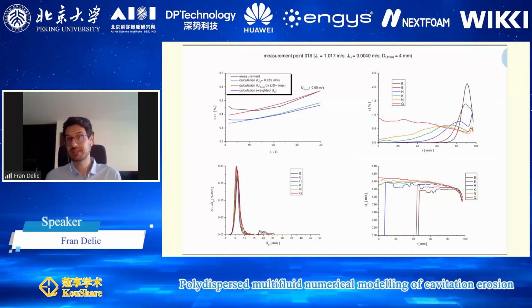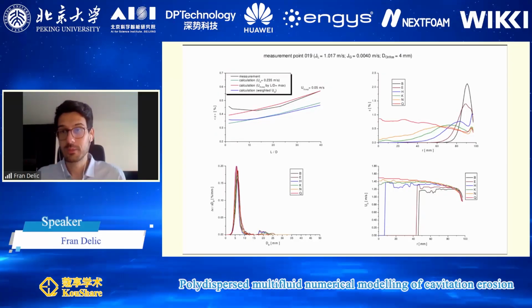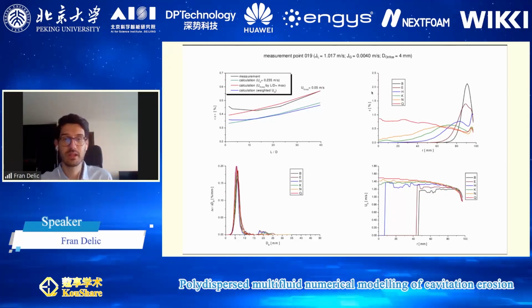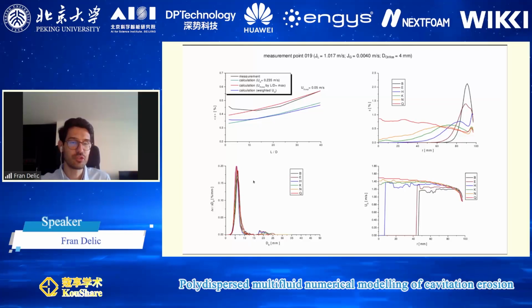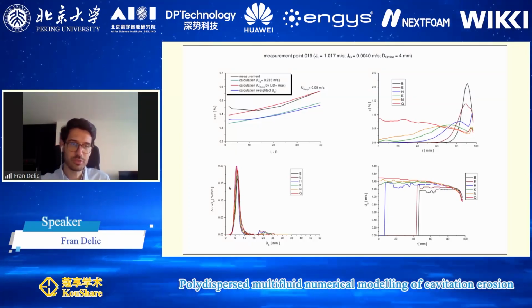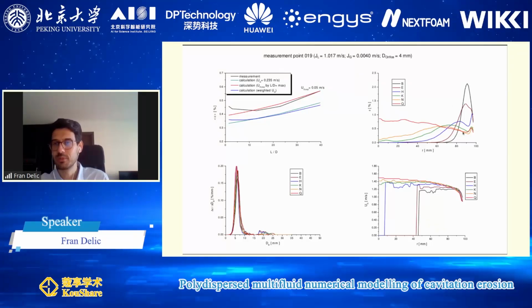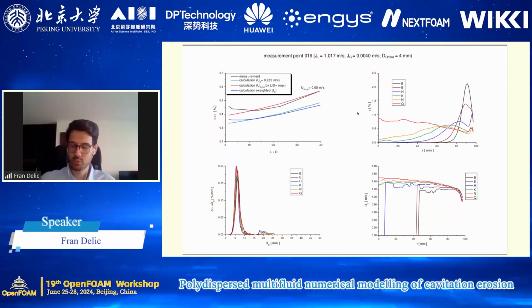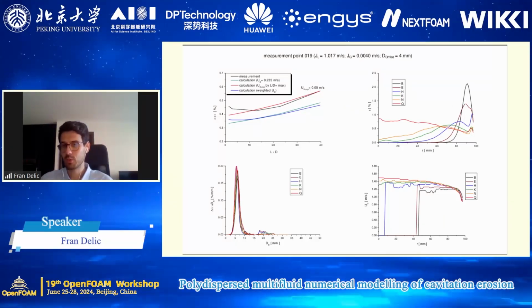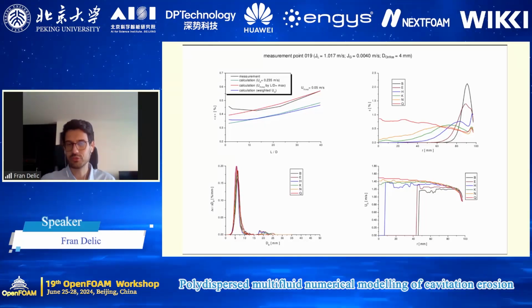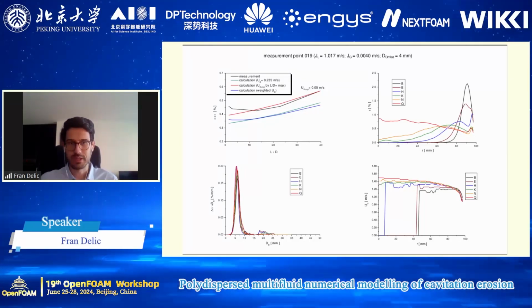And this is the exact same case, but the injectors are 4 millimeters in diameter. So similarly, the distribution is on the larger size. The average bubble size is larger, but more dispersed. However, you can see that the bubbles start near the wall, but they tend towards the center. So the different behavior, being wall-peaked versus centered, is exclusively due to the difference in the bubble size.